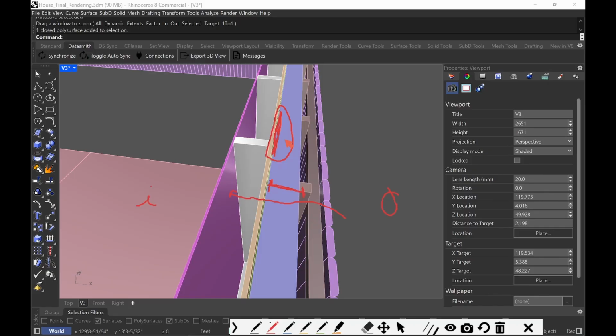So depending on the climatic regions, you need to know two things, right? You need to know how much insulation you need if you're going to do it for purely exterior, and you need to know the level of permeability that you need for your barriers. Obviously, for your air barriers, you want to not let air in, but that's just two important factors to understand. Now, some people will critique this and they'll say that if you don't put in cavity insulation, the difference of temperature is going to be too drastic that it's going to create a lot of condensation.